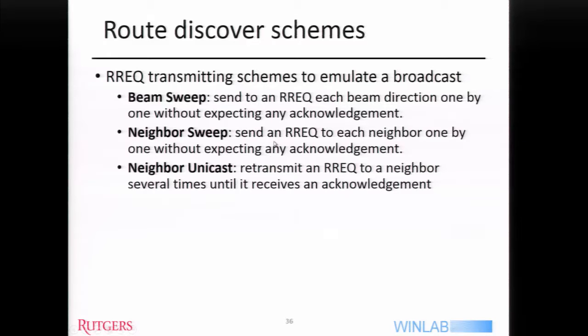And then you end up with a problem of dwell time, right? Because there's going to be an estimation problem. In order to decide whether the beam is there or not there, you need to integrate N of SNR. The more directions you have, the less SNR per direction. Yeah. So the longer it's going to take. So that's why it's a little tricky to do sweeping if you keep track of time and signal-to-noise ratios.